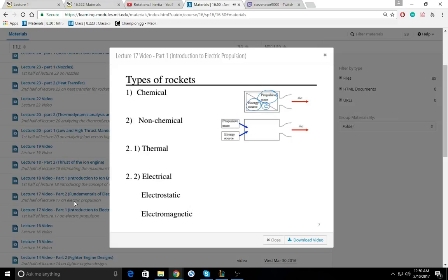So basically, we have a combustion chamber in which we raise up the temperature of the propellant, and then we expand it thermodynamically using a supersonic nozzle to an exhaust speed C. So if we do an enthalpy balance between the combustion chamber and the exit speed, we have that the enthalpy in the combustion chamber needs to equal the enthalpy at the exhaust. In the combustion chamber, in the same way as in gas turbines, the velocities can be considered very, very small.